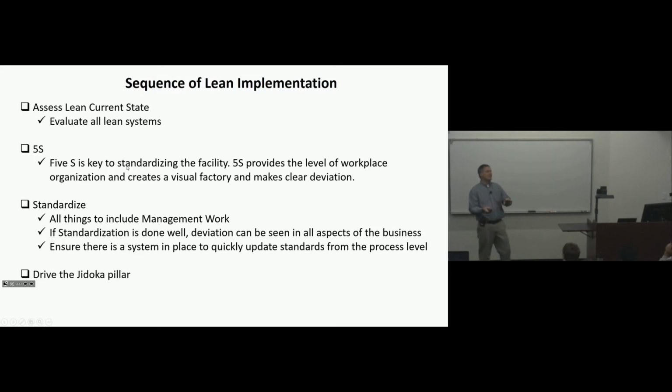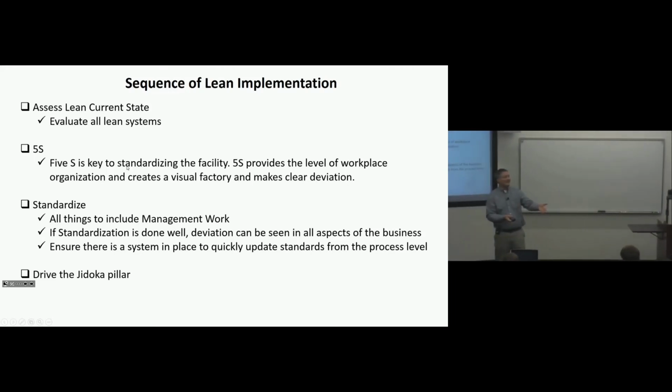I'm error-proof. Then when it goes to cell 2, we have little Raspberry Pi cameras that are inspecting to make sure all the blocks are correct. So that's not mistake proof, but it's still Jidoka. I might make a mistake, but I know it in station, I can fix it. And then when we go to cell 3, we may just have andon. Pull the cord if you see it, but we know people don't see defects, right? So we have a robot at the end with a camera fixed to it that's doing an inspection before we deliver it. Now I don't have Jidoka, but I have control within the cell. So I've implemented other things besides train real hard and be real careful, right?